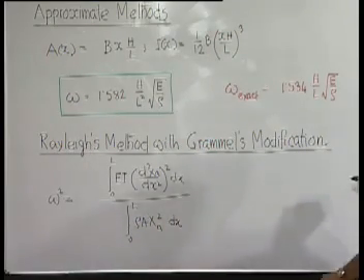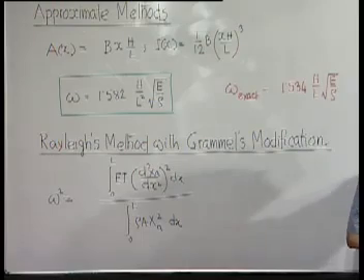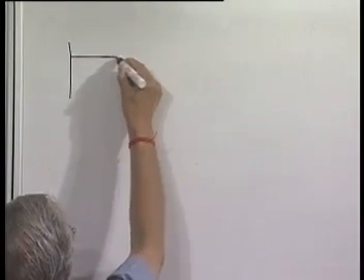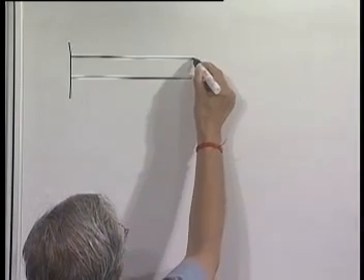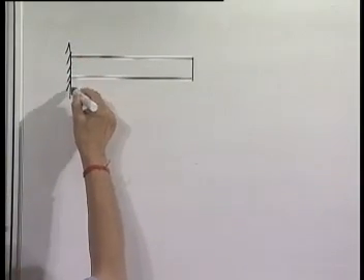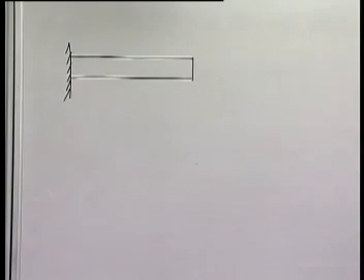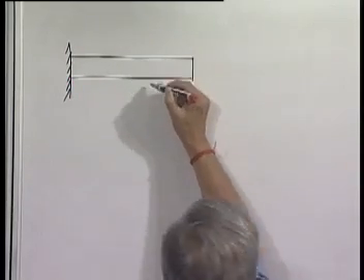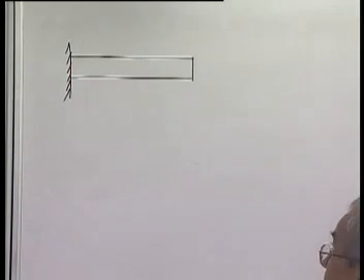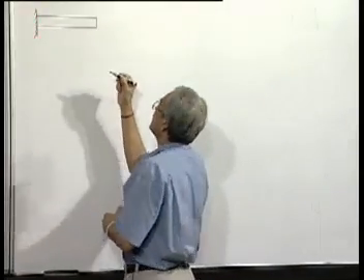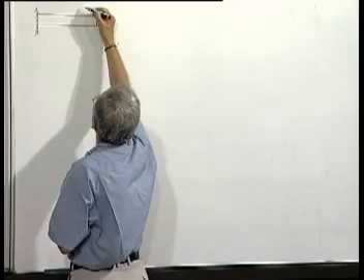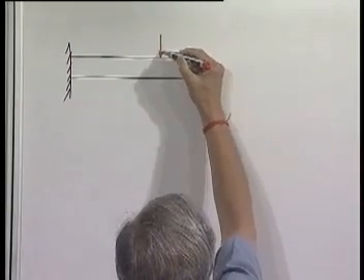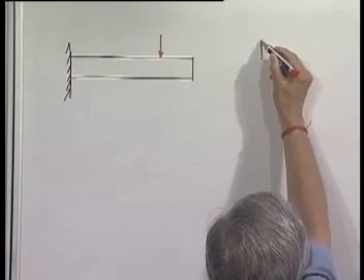Say for example, any kind of beam, but we will take an example like a cantilever. So what will be the inertia force acting? Inertia force acting on any particular element will be the mass of the element into the acceleration of the element at that peak point, that is peak acceleration, minus. So it can be either in that direction or in this direction. So it will be something like this, inertial loading. And this inertial loading can be written as